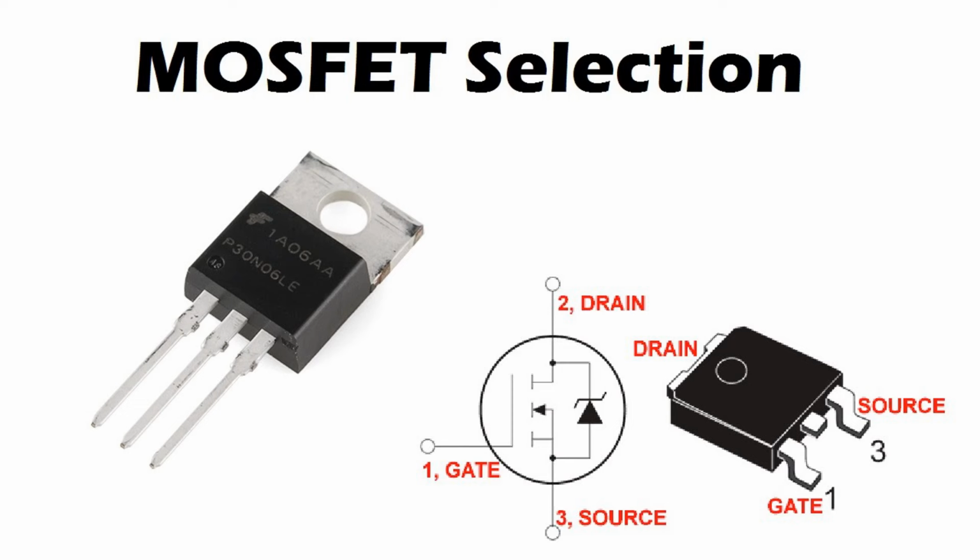Key features of the structure. Planar versus trench structure. Planar structure: traditional design, where the gate is above the channel. Trench structure: the gate is formed in a trench in the silicon substrate, which allows for better packing density and improved performance, particularly for high-voltage applications.